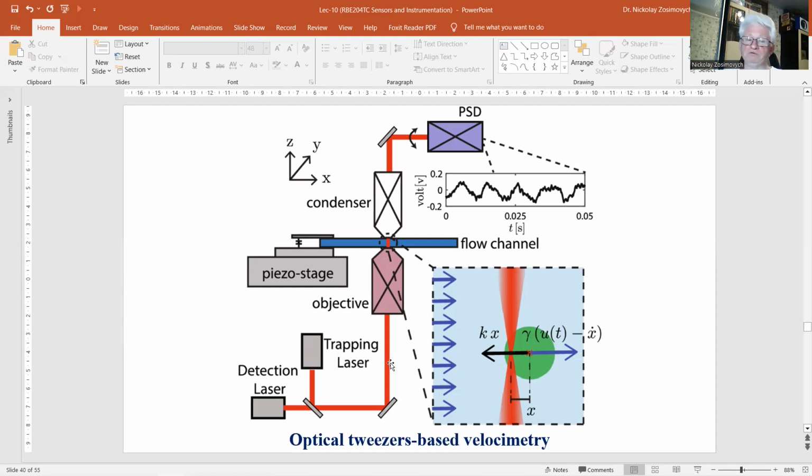When the object moves with velocity v in the plane of the grating, the output of the detector contains a frequency component equal to kv over p, with k the optical magnification. A velocimeter is described that uses this principle.